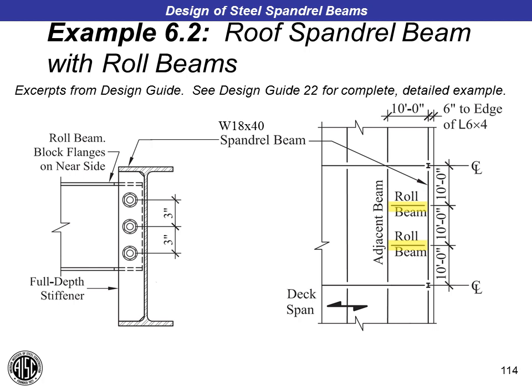All right. So let's actually stay on this same slide for the next question. And this question makes use of the word kicker, but we'll pretend these roll beams are kickers in this case. And the question is, in addition to providing lateral kicker, a portion of the tributary distributed torsion goes to the shear tab connection. I believe that is referring to the shear tab connection to the column. Do you typically add a kicker here, or how is that dealt with?